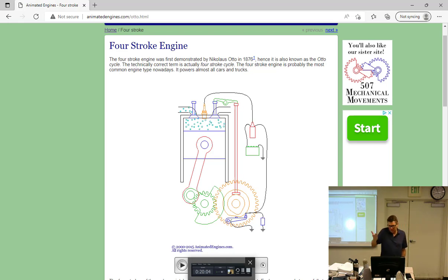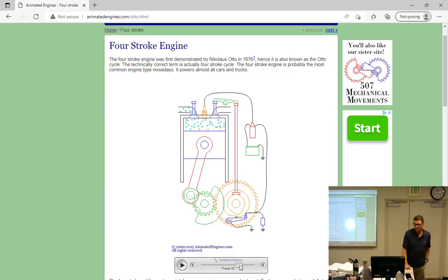And the inertia of the crankshaft and the pistons and all that weight is going to carry this up. So the spark plug fires right there, and the fuel and air starts to burn. It does not explode. If it explodes, that's called a detonation, and it actually can destroy an engine and eat through a piston in seconds. Detonation is really bad. You want a slow, even, controlled burn. So it starts to fuel, it burns out slowly.